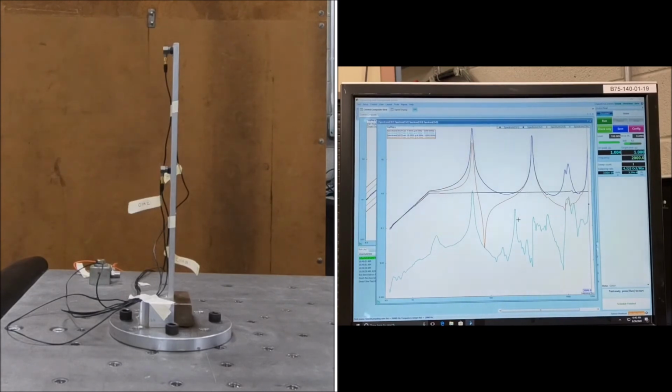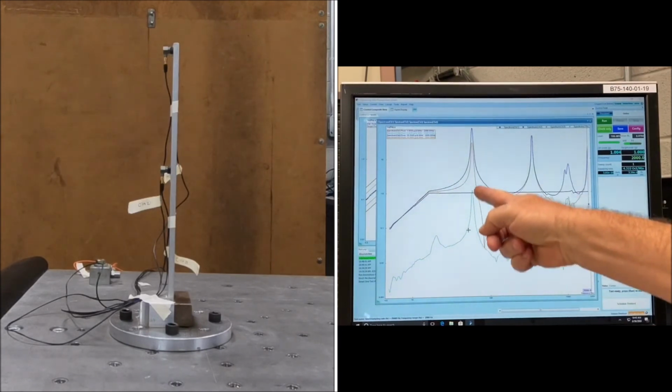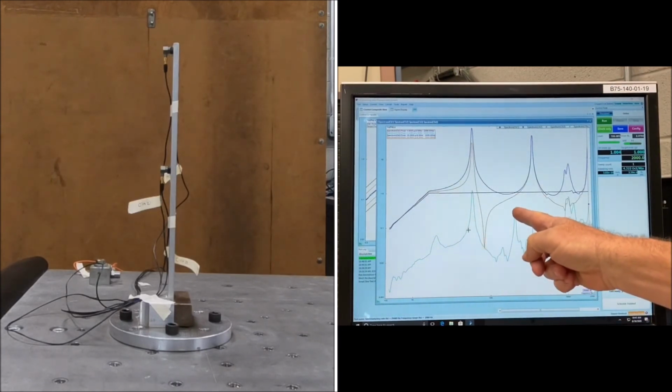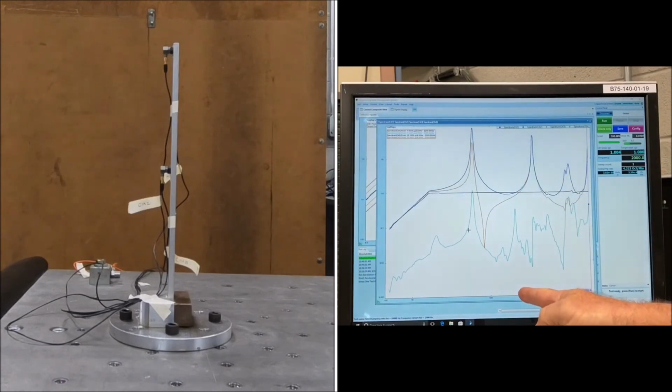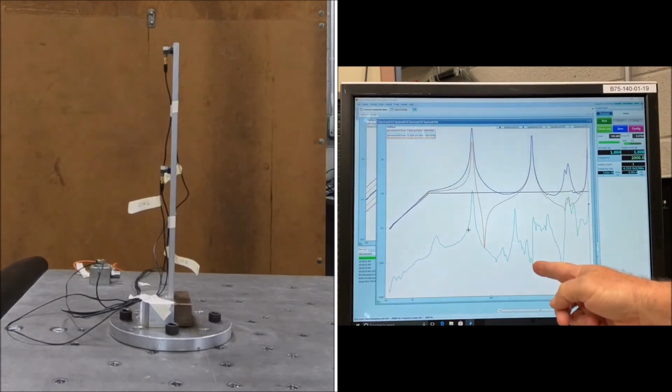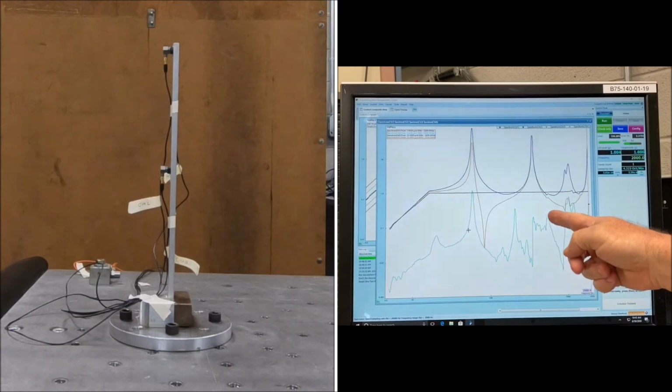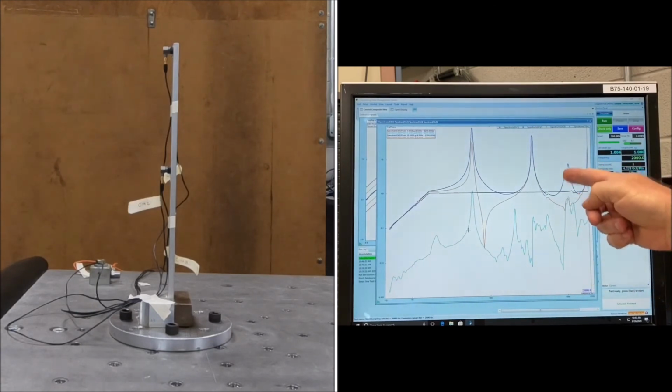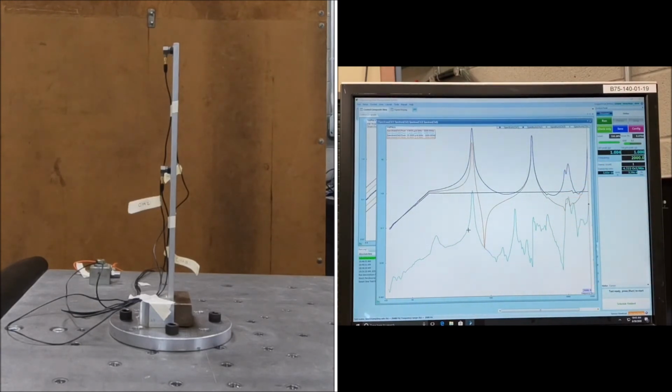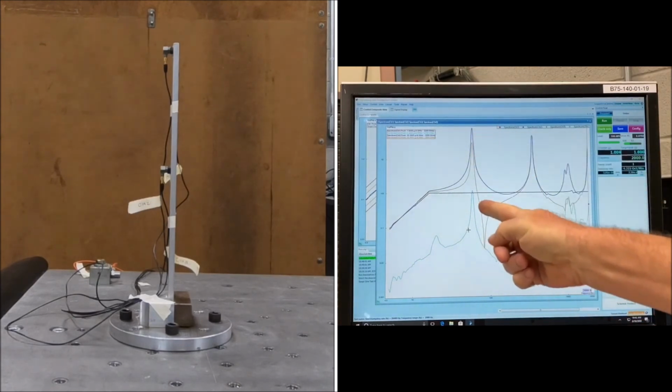So when we're counting resonant peaks, the first peak is right here, somewhere at around 60 to 70 hertz. The second spike is here, probably at about 200 hertz. And then we've got another one out here, and one out here. So those are the resonant peaks that we're concerned with. The primary one that we actually picked up is right here.